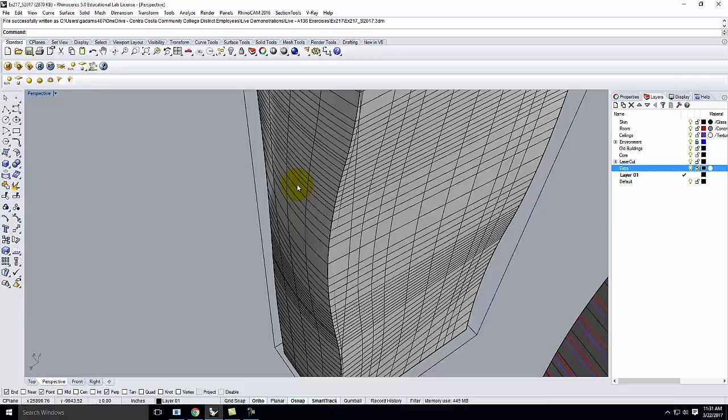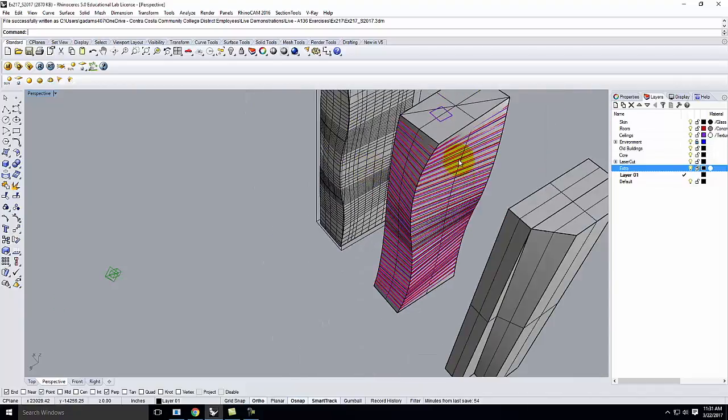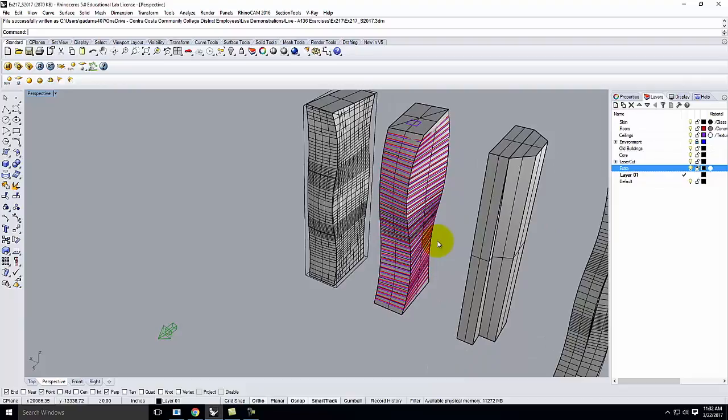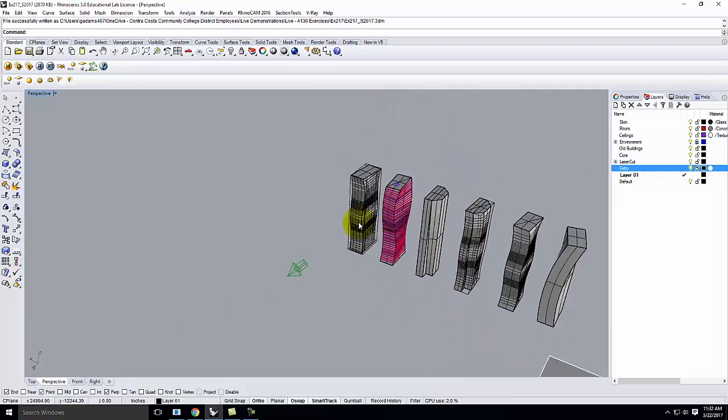You can't peel an orange and have the resulting peel lay flat without splitting it somewhere. Right? You end up making a little spiral and then it would lay flat. But in the process of making that spiral, we have some problems. It's not truly accurate. These straight line, what are called ruled surfaces, are very, very easy for Rhino to unroll and to use. And so we're going to go through the process of creating these unrolled surfaces.